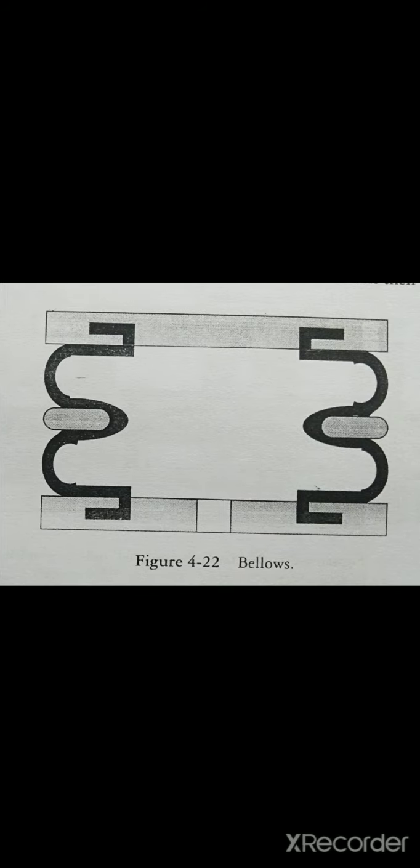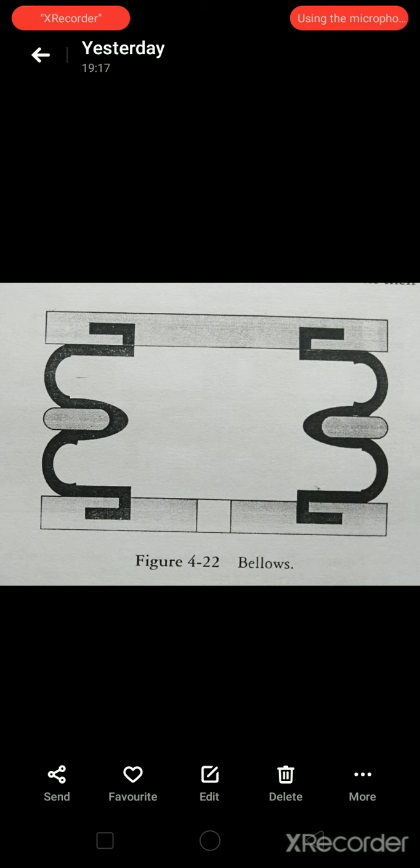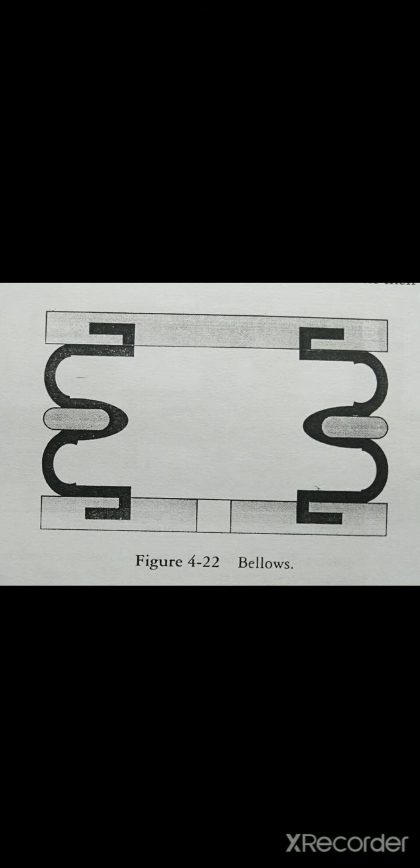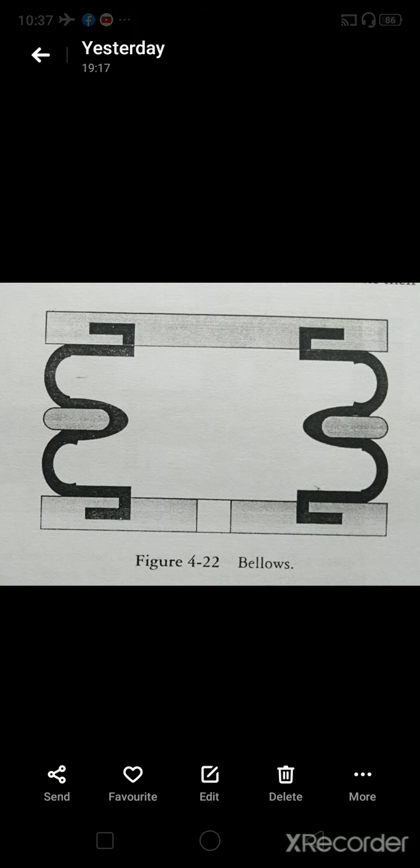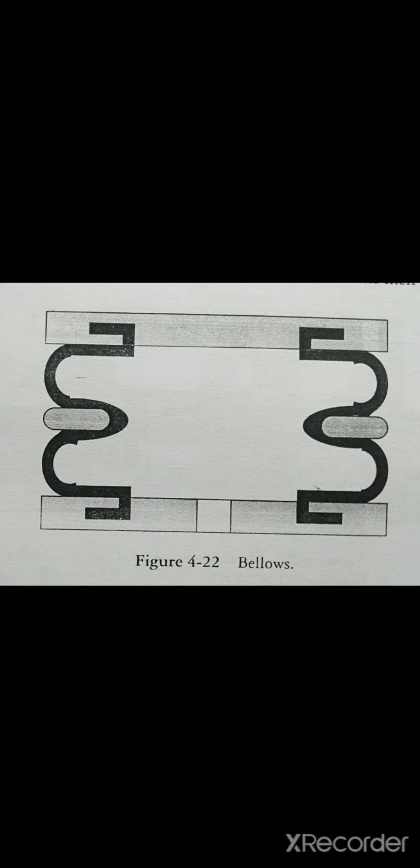Now you can see bellows actuator. Bellows actuators are durable like single acting actuators. They have no reciprocating parts or sliding seals, and hence they are virtually frictionless, maintenance free units. These actuators are designed with 1, 2 or 3 convolutions, which make their installation easy.